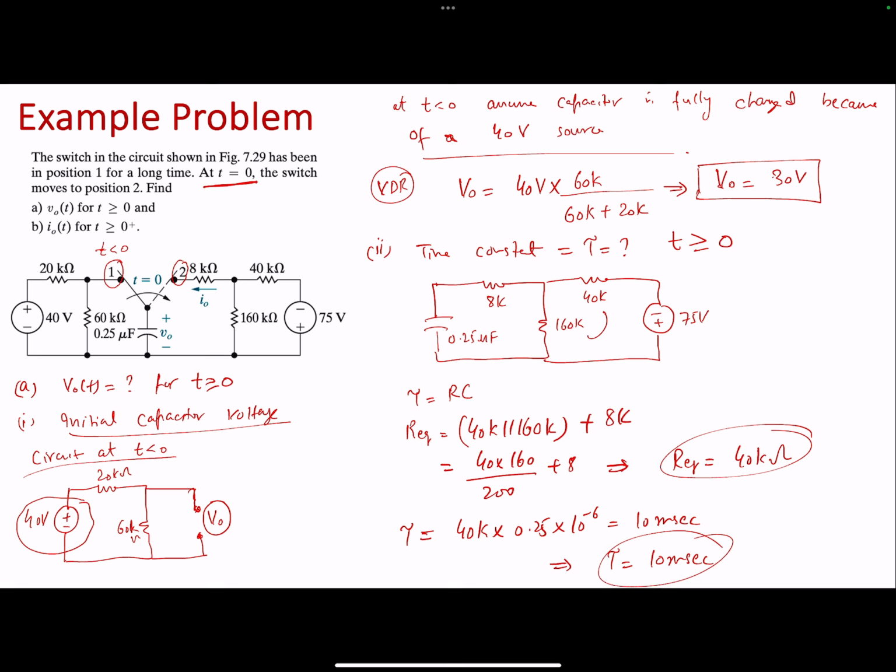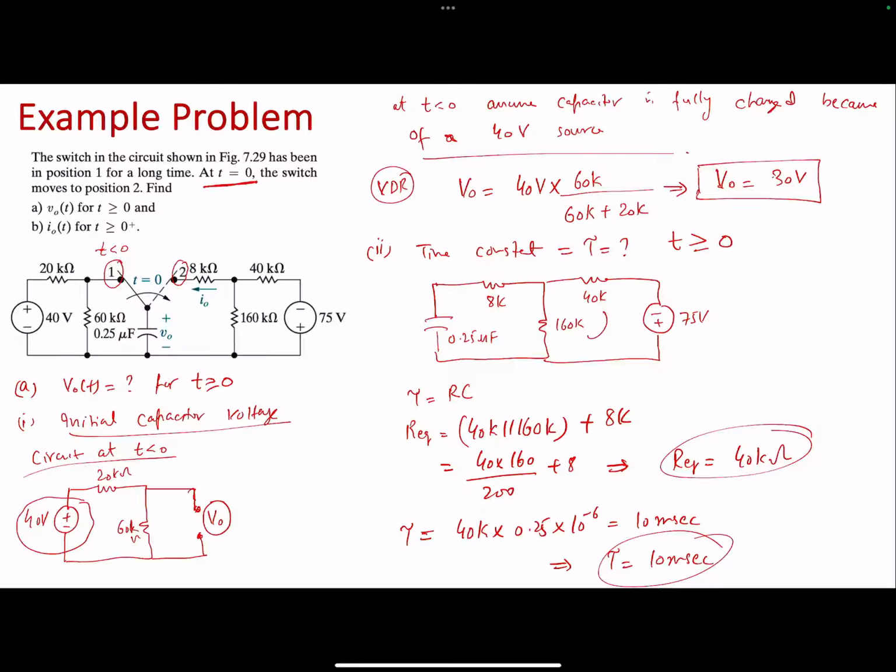So we ended up finding, no, the third thing is still to be figured out. What is the final voltage value, before we write down the equation? The third thing is we need to find the final voltage value, and again, this is found at time t equals infinity. At time t equals infinity, your switching event has already happened, because that happened at time t equals 0. So we are essentially talking about this circuit, at time t equals infinity, a very, very long time. This means that my capacitor should become an open circuit again, because a new steady state has been reached.